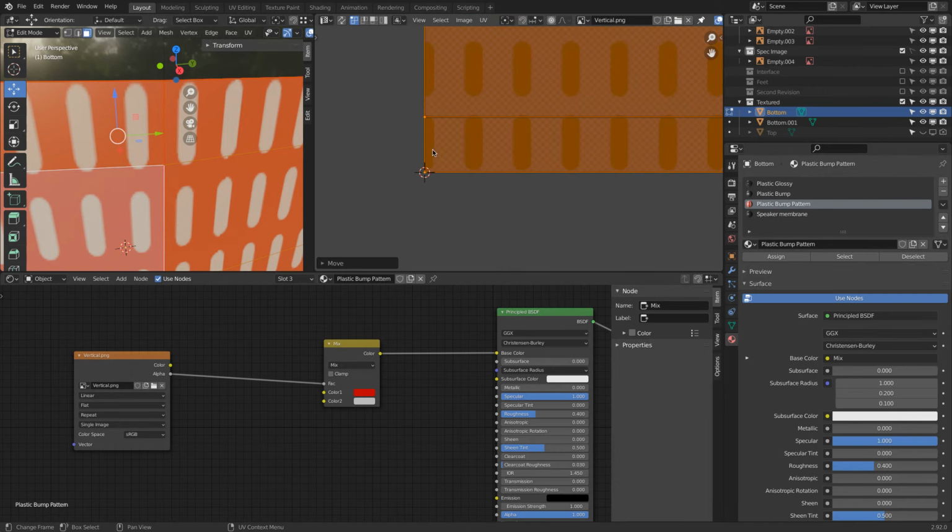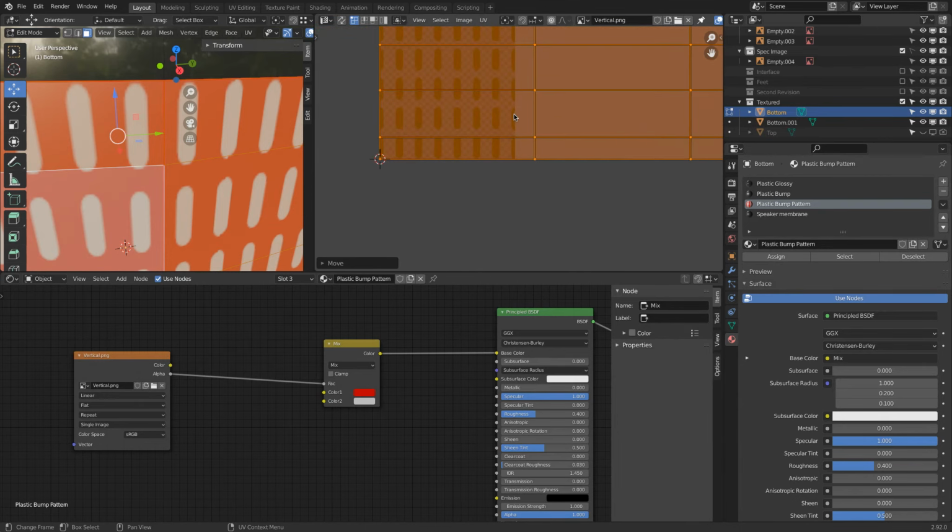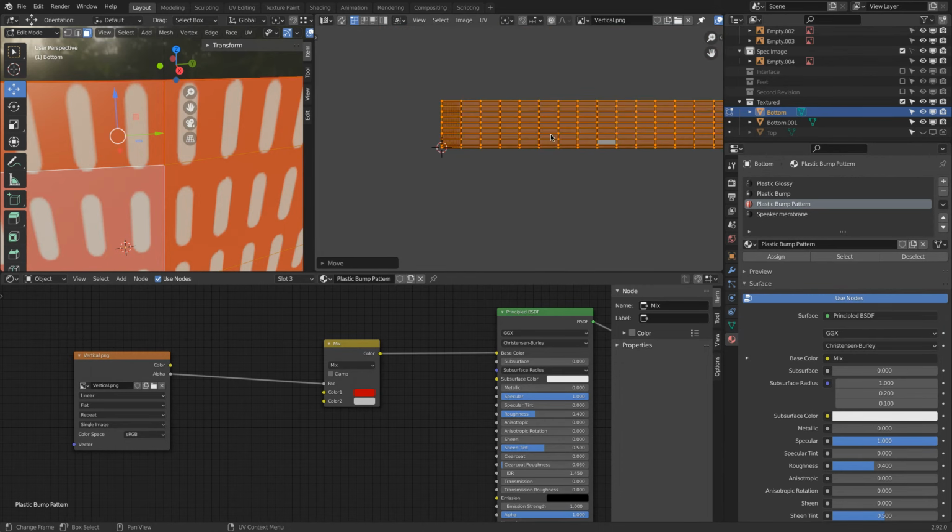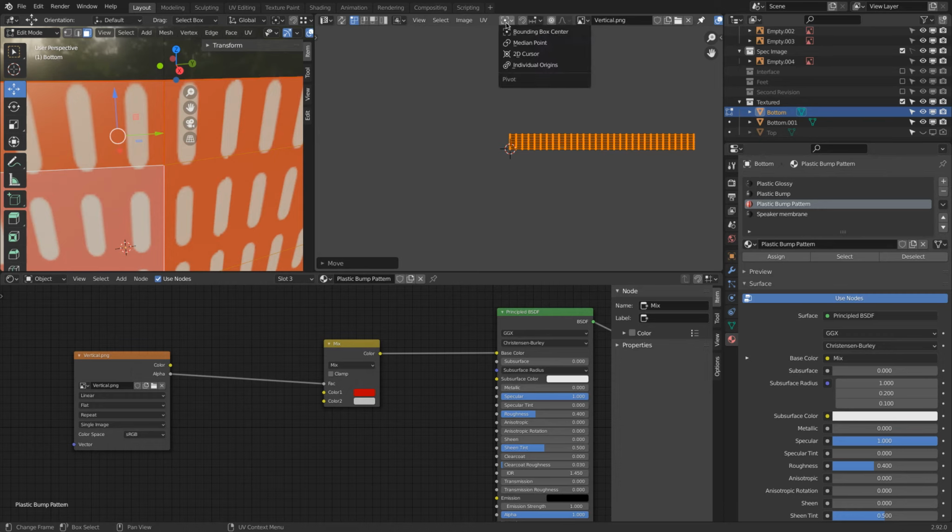So you see here we have half, full, full, full, full, and there we have half. And this image will be stretched over all the geometry. And this piece then will tile, and then we'll be at the end there. So just so you can see what's happening, I will set my 3D cursor to here. Click this point. In case it's moved, Shift S cursor to selected.